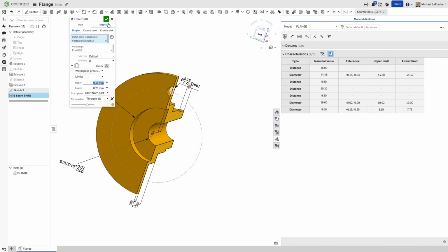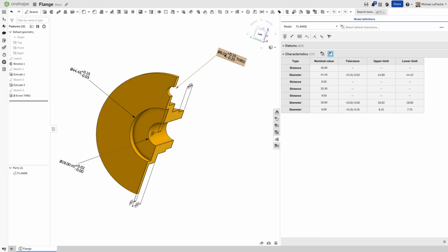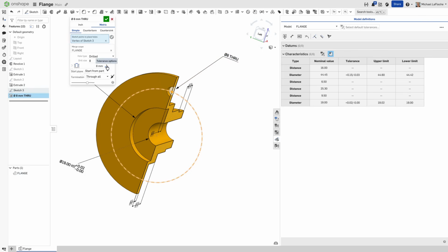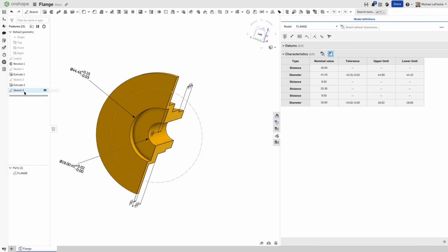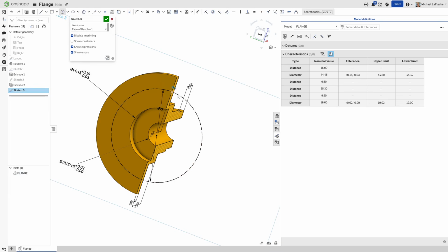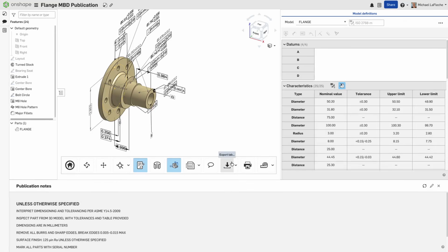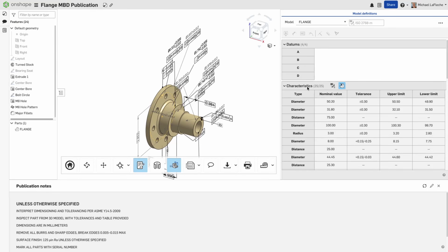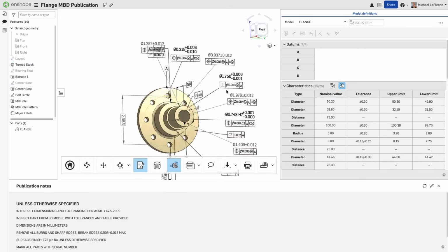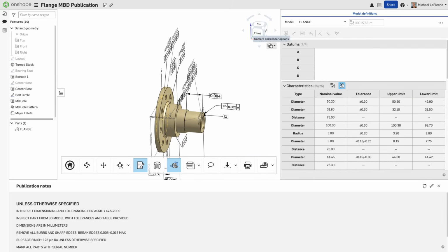All right, let's drill a hole right through here. We can make that tolerant or not, and apply tolerances just like so. It's pretty cool that you can do that right in the hole feature. It shows up in your characteristic list as you place this information in. Adding geometric tolerances, of course, you pick the feature itself and you can apply the geometric tolerance, like a true position tolerance or surface flatness, directly to the faces of the model.